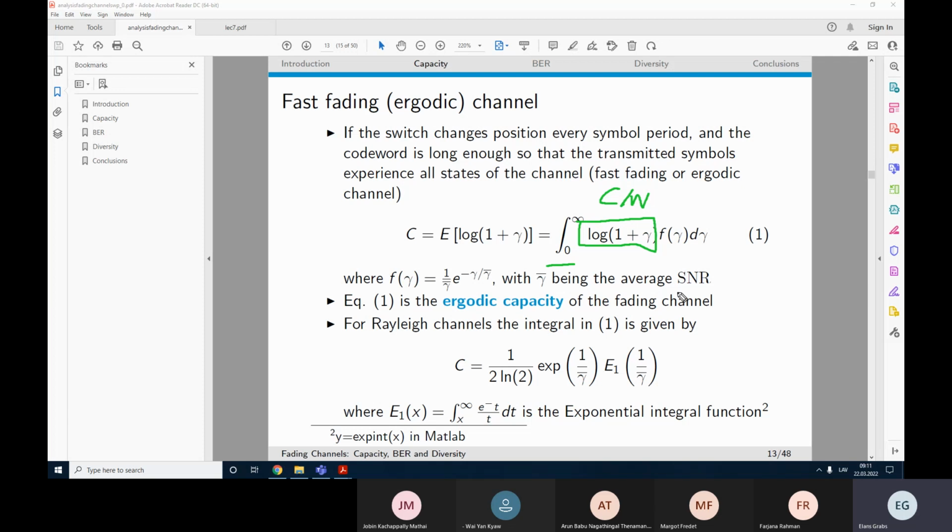We usually divide by the bandwidth because we don't want to be tied to some specific bandwidth. As you know, we use some filters which we have calculated. For example, the same root raised cosine filters we simulated last time, and all these filters have a specific bandwidth. That means that the system that uses this filter will also have a specific bandwidth.